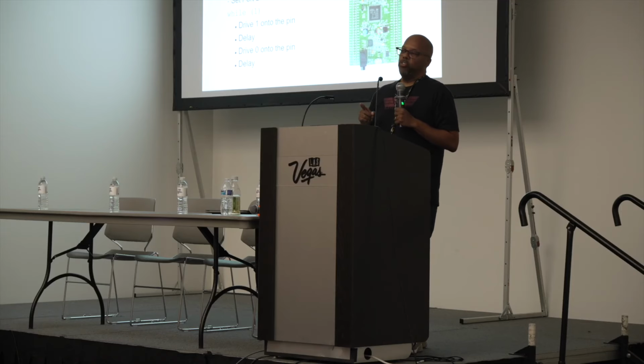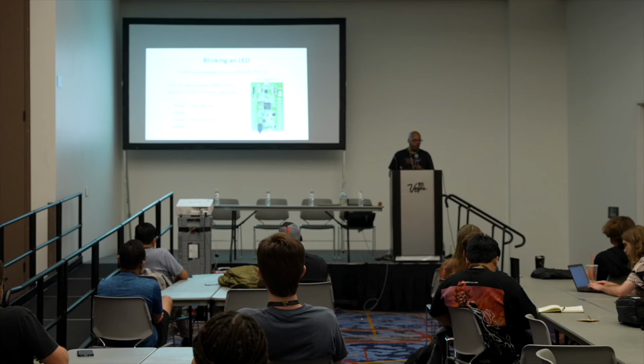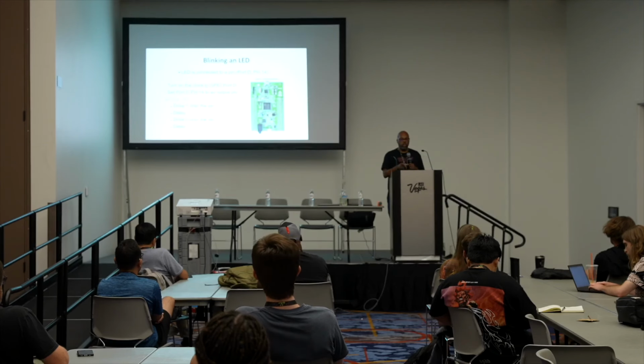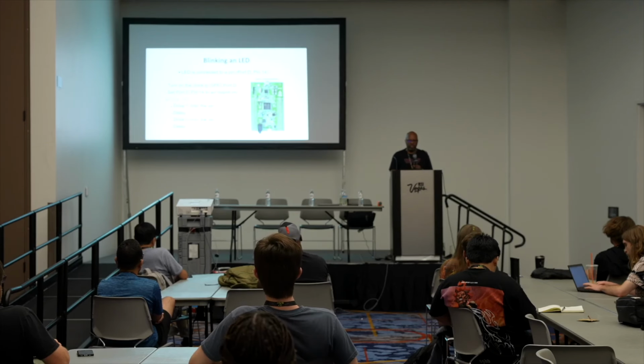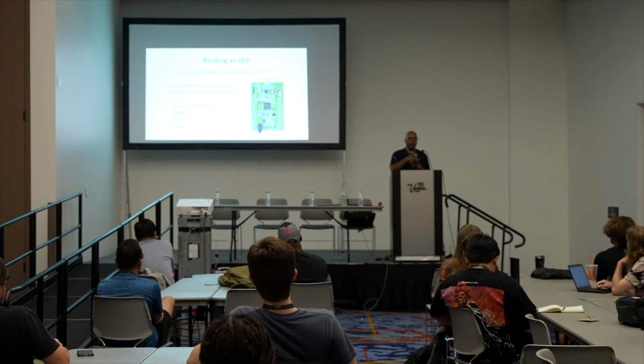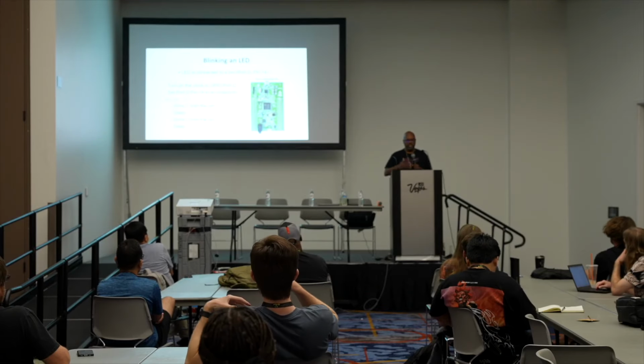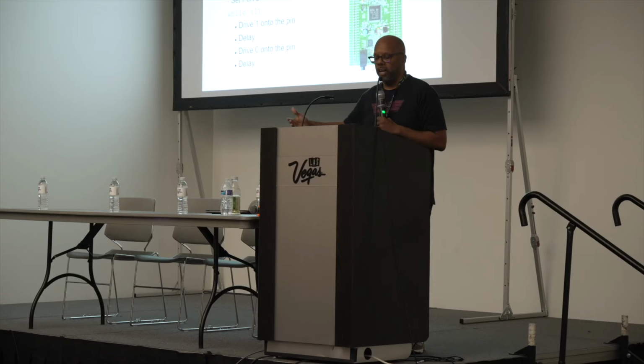What they do a lot with these peripherals to save power is they turn off the clock to these peripherals. A clock is a square wave that determines the rate at which events happen on the chip. If the clock is going, it is consuming power. So they shut off the clock to peripherals that are not in use by default. And so in your code you have to turn on the clock to the peripheral before you can use it. Again, there's some register where you set a bit, and it turns on its clock.